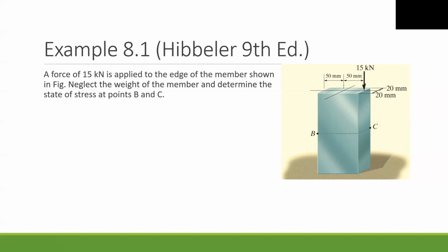A point force is applied at the top of the column. The value of the force is 15 kilonewtons. In the question, we need to determine the state of stress, the resultant stresses, on points B and C, like these points.